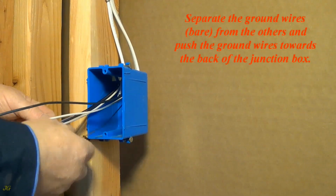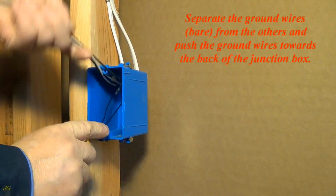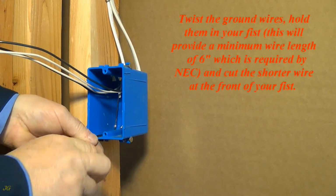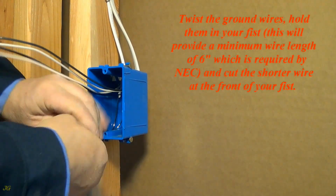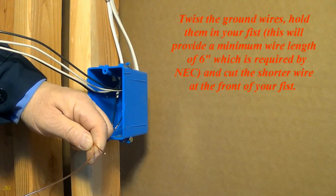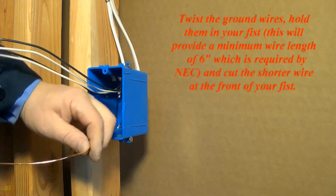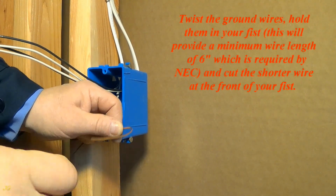Separate the ground wires, bare, from the others and push the ground wires towards the back of the junction box. Twist the ground wires. Hold them in your fist. This will provide a minimum wire length of 6 inches, which is required by NEC, and cut the shorter wire at the front of your fist.